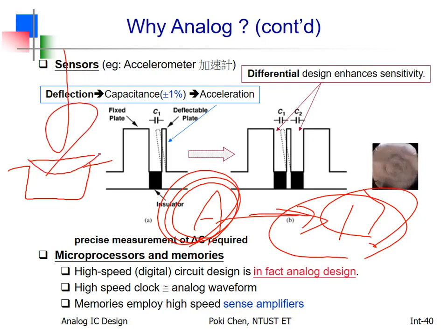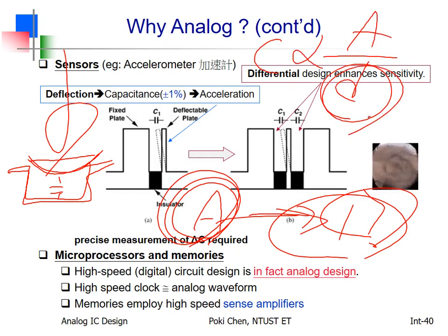You will get more deformation. What does it mean? The capacitance between the membrane and the cavity will be increased, because the distance between the membrane and the cavity will be reduced with higher air pressure. That is one kind of air pressure sensor. We have quite many sensors anywhere.